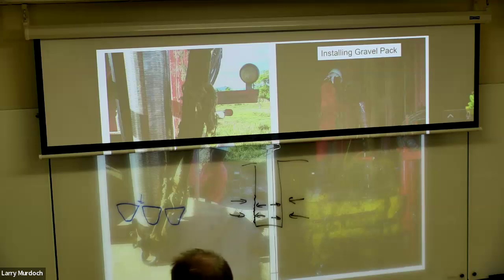And then we talked about the materials that are used to create wells. So bentonite is an important material because it forms the seal. I'm going to send around two, we'll go different sides, but these have these gray particles in them. This looks kind of like gravel, and this looks like sand. But these are bentonite. Bentonite is clay. Clay is very, very small particles. You can't see clay particles with your eye. So this is bentonite, many clay particles pressed together and dried and broken up.